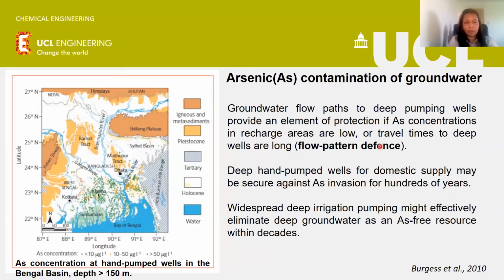Those things are very important, and students of water management should be acquainted with them. When you start using the deep hand-pumped wells, you are making opportunities for vertical flow of water between the layers, because the layers of rocks are different materials.